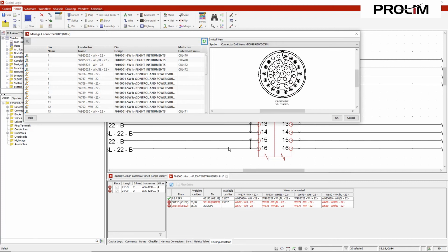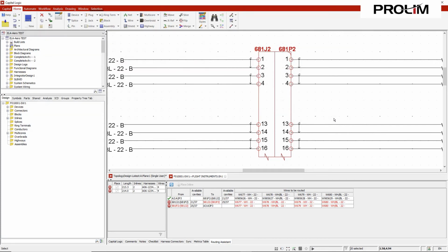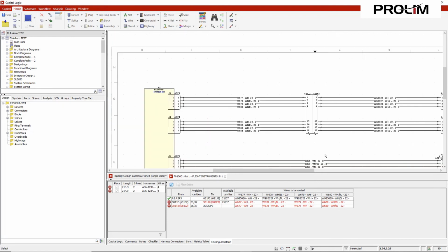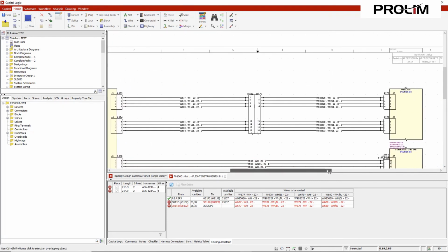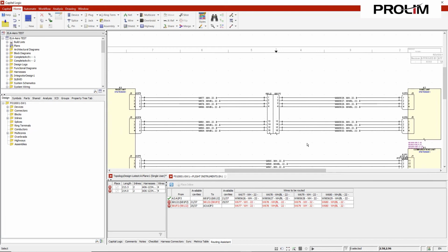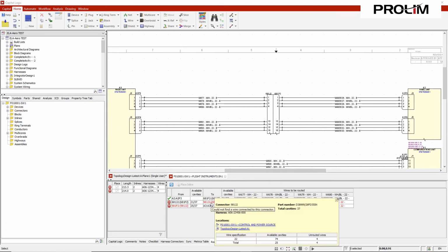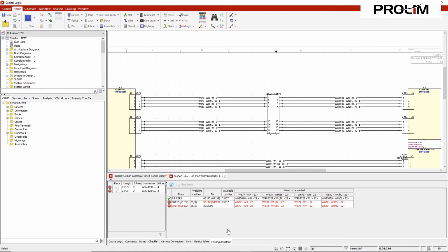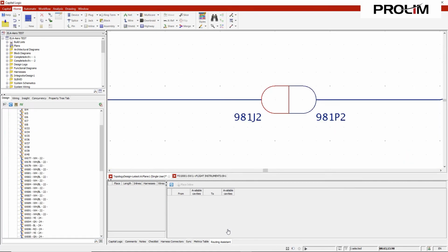And what you saw there is we actually told the software that we would like those wires to run through this particular inline because we had multiple choices that it could run through, and it automatically places that inline back into our system wiring designs. And we know that that's the correct path because we've seen it in the context of the aircraft topology. Now from there, we don't even have to go back into the topology plane.